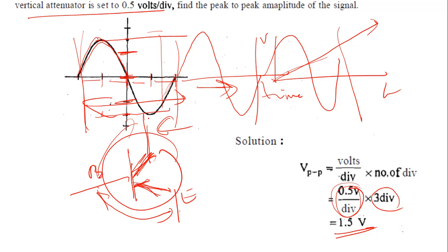If the DC voltage given to the amplifier fluctuates, then the biasing between emitter and base will change randomly, and you will not be able to get the desired amplification. Sometimes, depending on the emitter base biasing value, the amplification may be large and may be low. So most of these semiconductor devices require a fixed biasing voltage.